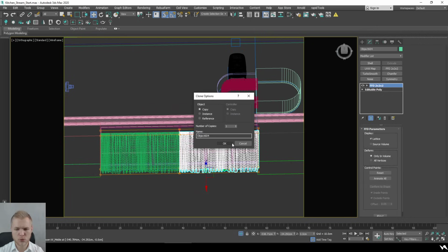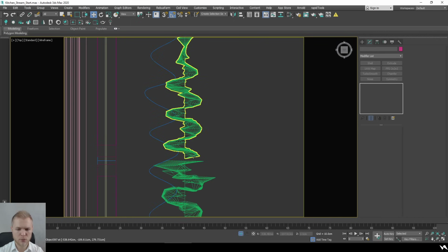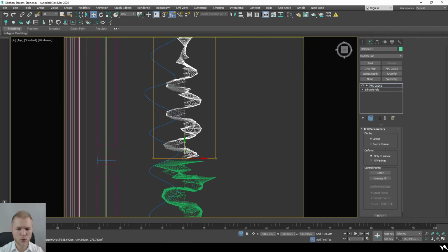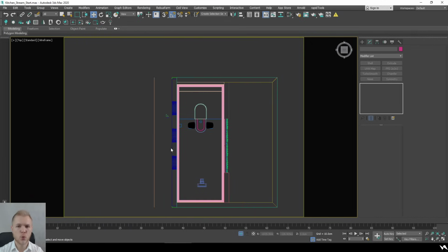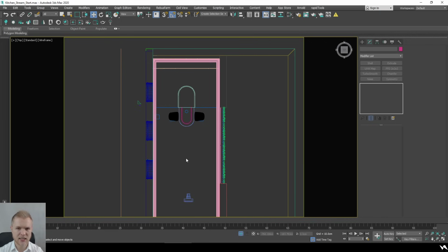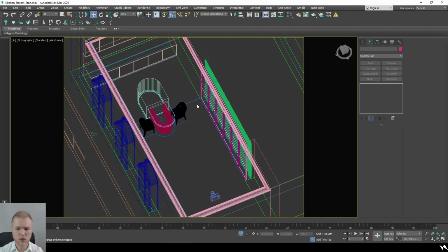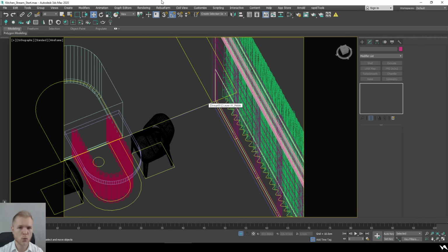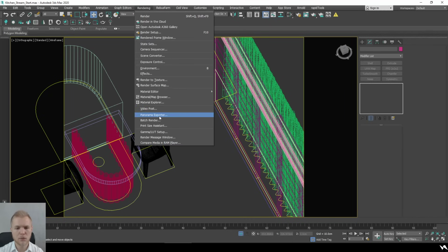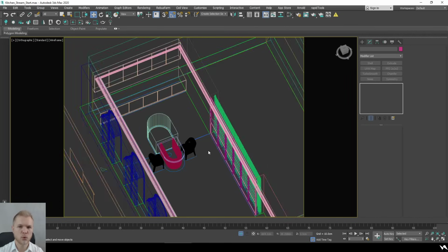So to answer it short, to sum up the answer, I would say that working with Gamma 2.2 is actually a better solution. Why? Because most of the models and most of the resources that you're going to find on your way are going to be created in that technique. Going back to 0.1 is just going to be, well, like going back in time and trying to reinvent the wheel. It's not going to work, and there's a reason why 3ds Max actually moved from Gamma 0.1 to Gamma 2.2 as a default, because it just works well.